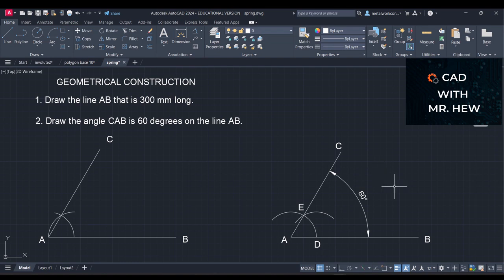If you have a 60-degree angle of a force being applied and you're doing it graphically, meaning you're drawing the solution with a t-square, set square, and compass, you could choose to construct the angle like this, or you could use a protractor that is in the geometry set, right? But if you are doing geometrical construction, this is how you would construct it using your compass, t-square, set square and pencils, all right?